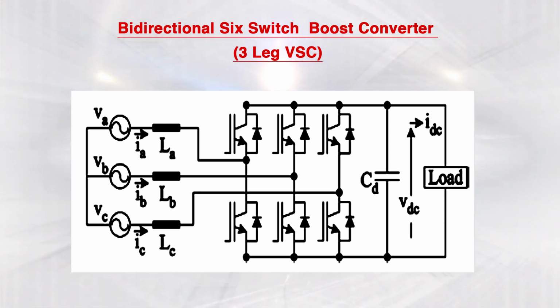So, it is also a single phase, as you could see we have a voltage source AC supply and it is connected with 2 legs, positive and negative. However, we can use one midpoint from the capacitor and it is connected with the 3rd leg of these devices. So, bidirectional 2 switch half bridge is also a popular topology. Instead of having 4 switches, we can utilize in one leg 2 capacitors and 2 devices. Using 2 devices, we can also make this type of converter.